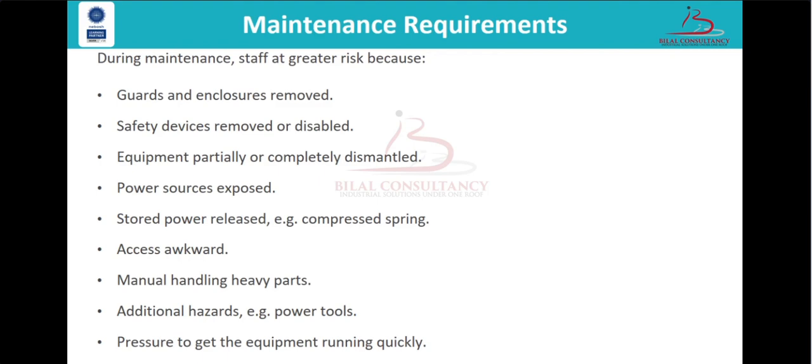A safe system of work should be developed for when maintenance work is carried out, and this may require the use of a permit to work and adequate levels of supervision. For some items of work equipment, it is foreseeable that deterioration of safety critical parts might occur, and it is possible for this part to be inspected without dismantling the equipment. It may be necessary to introduce some form of inspection regime.